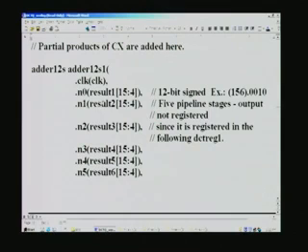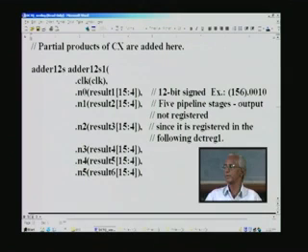So at this step, if you take the ModelSim results and ponder over the waveform, you will notice that it will be of the order of some decimal number, some 156. This is only a typical example given for one of the results, and other results will be hovering around this. The point here is that I want to point out that there is a decimal point here, and after this 4 bits. So it is a mix of decimal number and binary number. Just to point out the decimal point, after the decimal point there will be 4 digits here, and this adder, as we have seen before in the design, has only 5 pipeline stages, and the output is not registered.